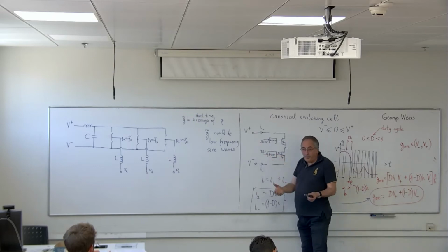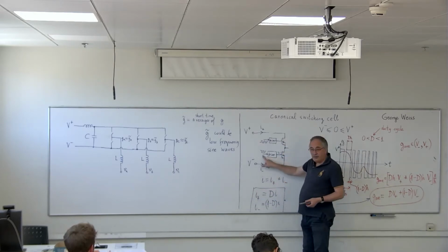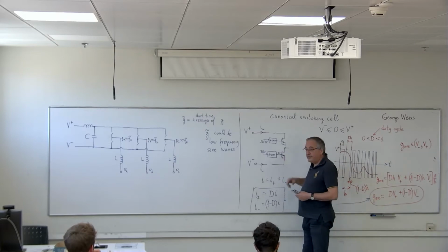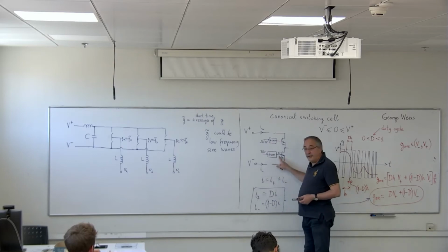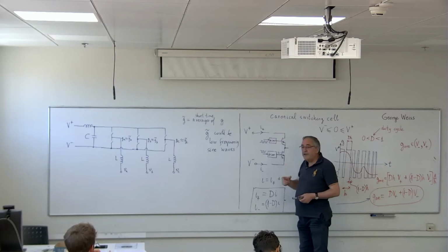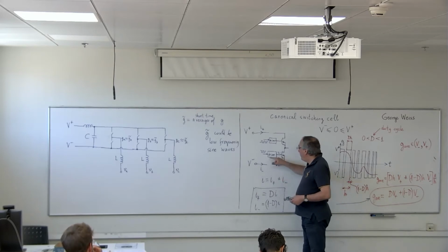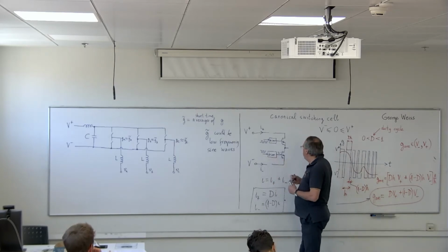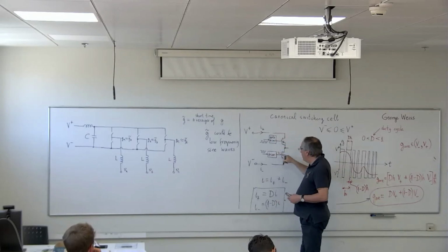But this is a logical signal. So it is typically between 0 and 3.3 volts, this signal. It comes from a processor. Whereas this signal is a gate signal for a MOSFET transistor. So it is typically of the order of 12 volts. So this is higher voltage and also much higher current. The current flowing here is very high. I will explain in a moment why. Whereas here it's only a signal, so there is very little current flowing. So this is, to be more precise, a gate driver. And this is also a gate driver.